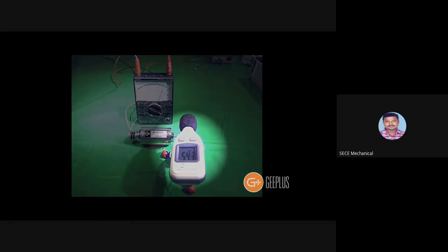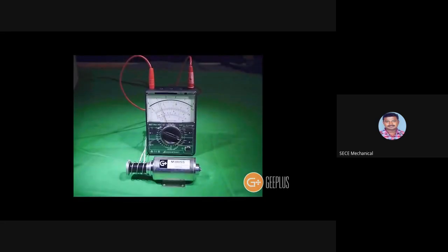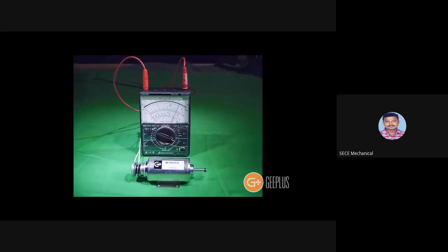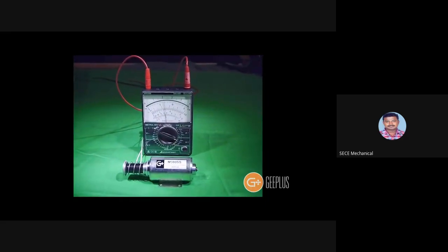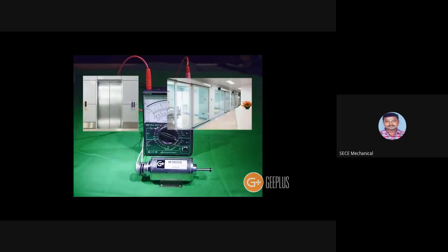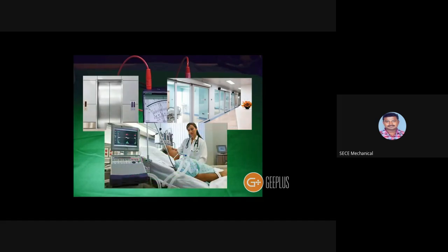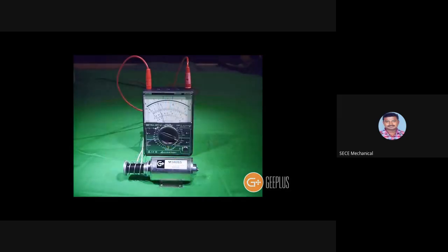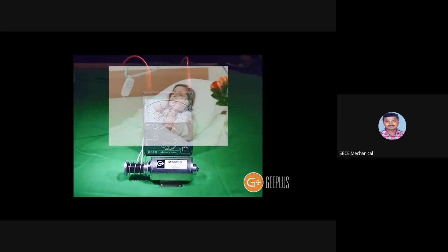Compare this to a standard tubular solenoid where the displacement impact causes a spike on the sound meter. This quality makes the superstroke solenoid useful in applications that require a reduction in audible noise. For example, in elevator doors, automatic doors, and locking devices that need to be silent, or in medical equipment in environments where patients are sensitive to noise. In some countries, controlling the noise created when performing seemingly simple tasks has become a regulatory requirement.